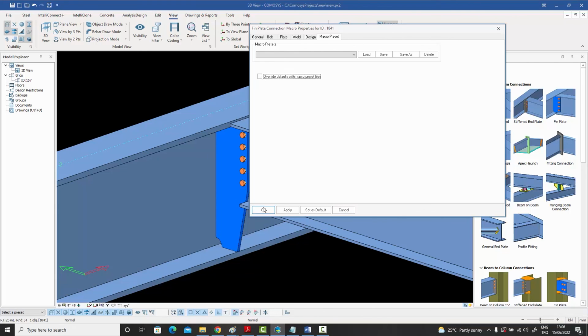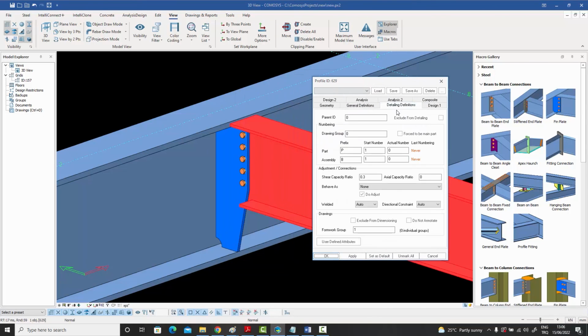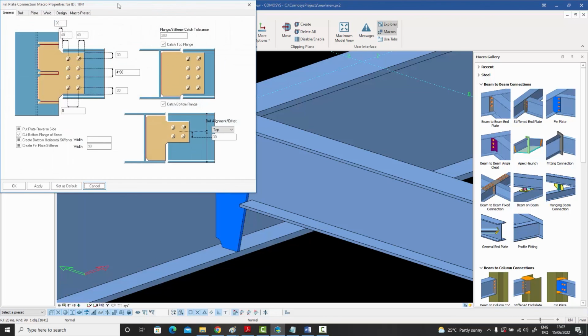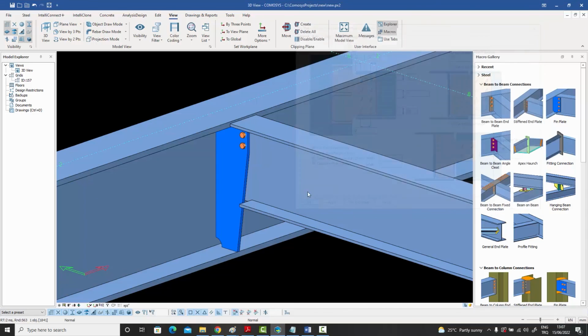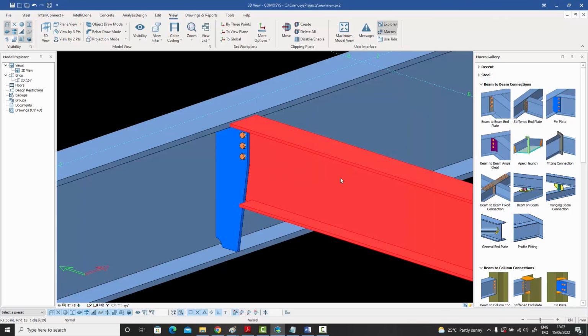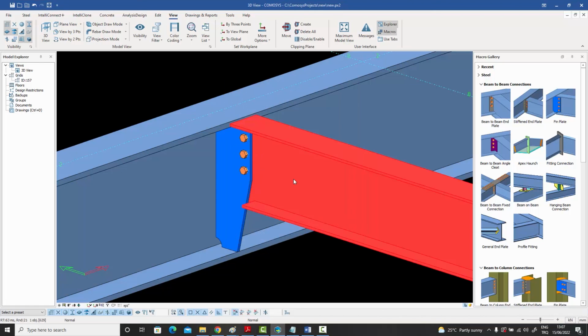So if I turn this off and say okay, and now go in and make a change in the detailing, say bring it back to 0.1, the reason that didn't work is because the macro already has loaded up those defaults, so I need to clear those defaults as well. Let me clear those distance related defaults like that. Yeah. So now it is actually doing some sort of an analysis, and now it's modifying. If I were to increase it further, now it's changing the bolt diameter, and right now it's doing that preliminary design which it does based on the material constants file and the load level.